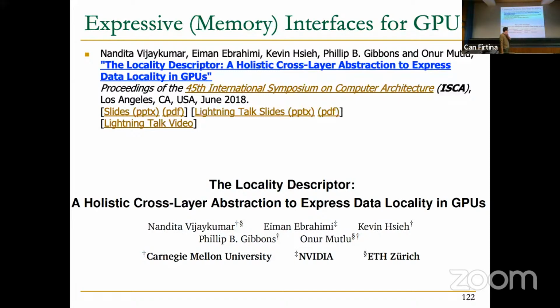But you as a programmer should be very careful about how you place data, right? Because there are large register files that are very close to the processor, in the end in the compute units, and you want to use them, but there are also on-chip memories with certain characteristics. So exploiting the locality in the applications and making good use of all these different memory spaces is quite challenging, but there might be simpler ways by providing the hardware with hints on how to access data in order to better exploit locality.